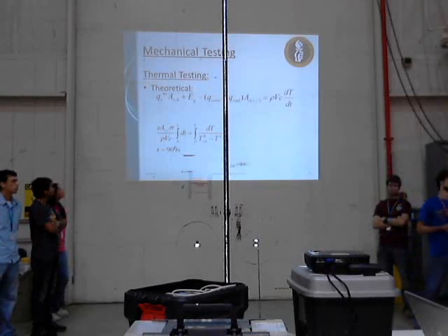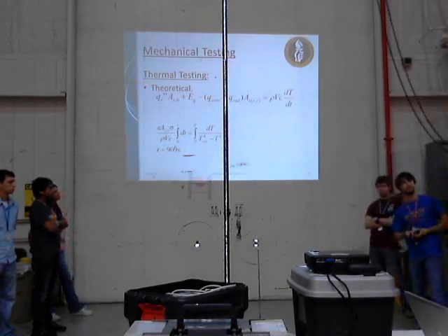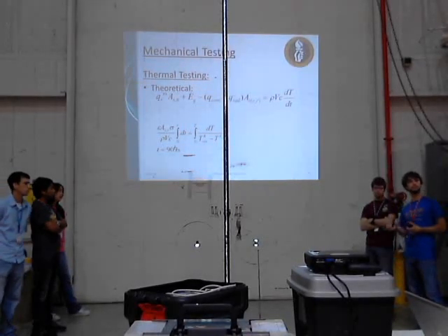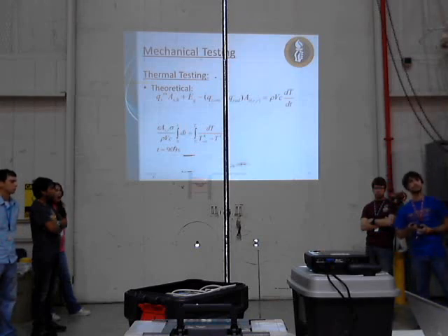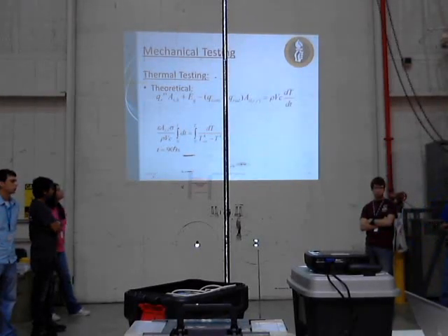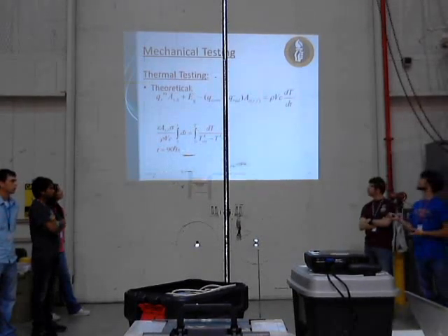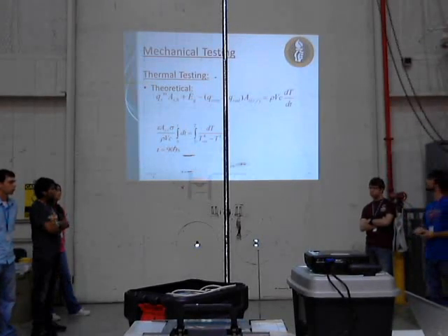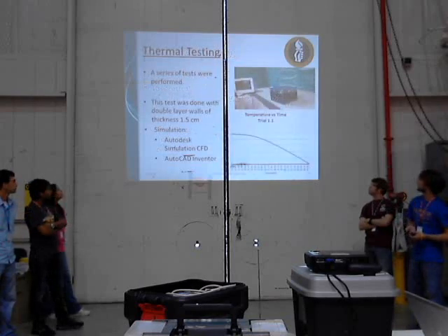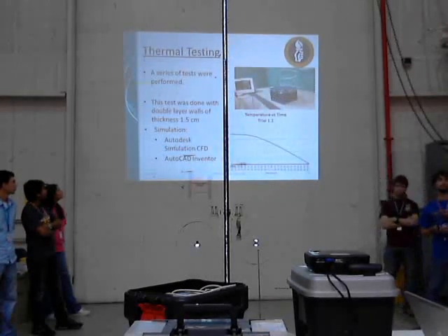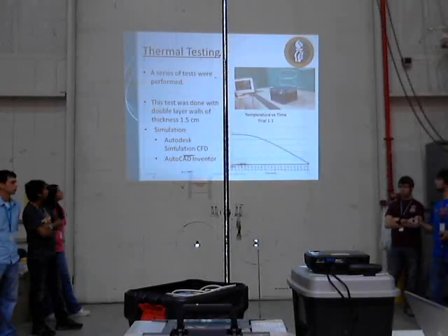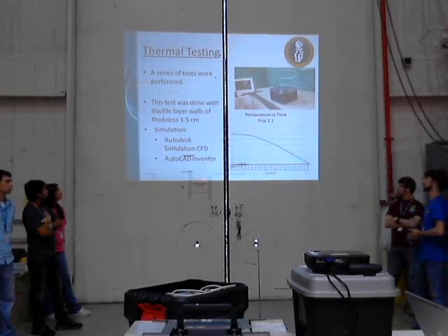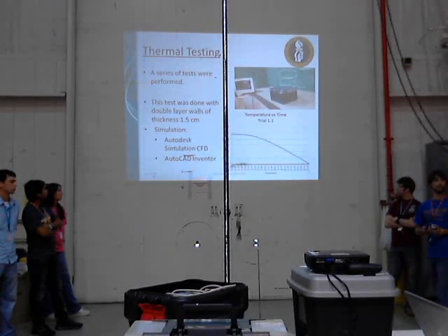So what I did was simplify it to only consider the radiation portion of heat transfer, largely because a lot of these sub-zero temperatures will be experienced where there's not a lot of wind, so convection won't be a huge factor, is what I assume. I came out to around 909 seconds using the volume of our lower portion, which will contain the important circuitry. After this, we built a test box and put it in a negative 80-degree freezer and saw how long it would take for the internal temperature to lower to 0 degrees Celsius, which is where a lot of our important components will fail.